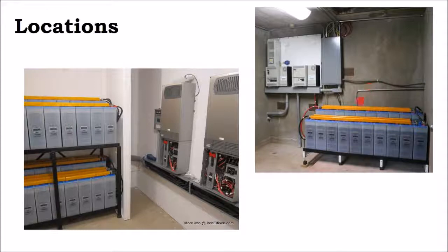The first is the deteriorating agents of these batteries could expose this metal conduit. And you can see this installer didn't care, because they're capping their batteries and ventilating the gas out of the building. But you can imagine a local inspector might say, well, that's not good enough. What I want this to be is electrician's gray conduit.